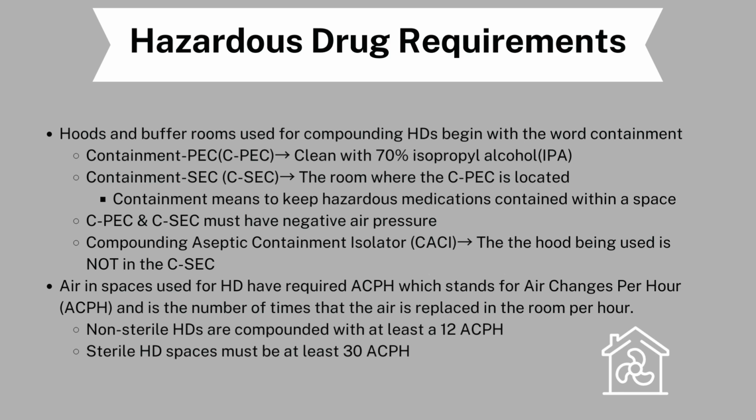Non-sterile hazardous drugs that are compounded need at least an ACPH of 12, while sterile hazardous drugs need spaces with an ACPH of at least 30 or higher.